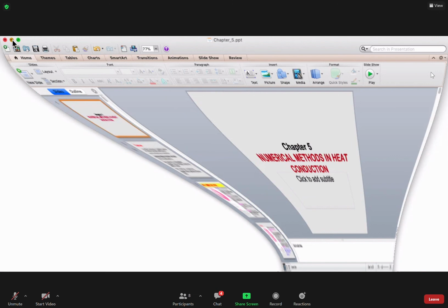When it's 0.2 or more, you can use only the first term. If you look at this equation, it is the same as this one, my friend, but only selecting the first term. When they select the first term, it is simplified to this one. If you use this equation, as I mentioned, the error is less than 2%. And it is specified again that this is only applicable when the Fourier number is 0.2 or more. This is the only time that you can use it, okay?